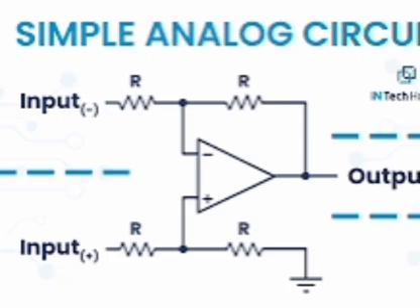Rectifier: an electronic circuit which converts a pure AC signal into pulsating DC, or which converts a bidirectional waveform into a unidirectional waveform. Ripple factor gamma: the amount of AC present in the output of a rectifier is called ripple. The amount of AC in a signal which contains AC and DC is calculated by the ripple factor. Gamma equal to RMS value of AC component by DC component. Gamma equal to square root of (VRMS by VDC) whole square minus 1.